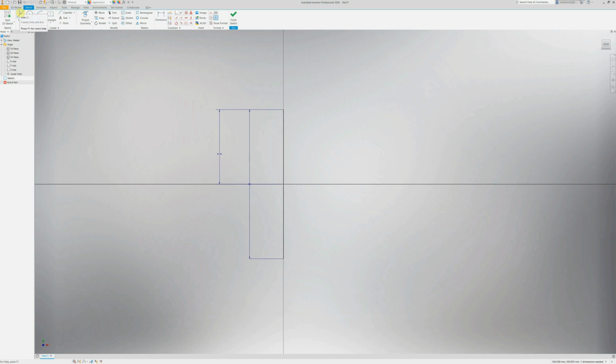So this is going to be a revolved component, so I'm going to be drawing half the profile and revolving it around this center axis. Now, to do that, I'm going to go back to the straight line, and I'm going to start from the top, the wide section at the top, and the outside diameter of this is 16mm. So I need to convert all my sizes here to radii. So 16mm diameter would make an 8mm radius. The height of it is 20mm. And then it steps down into a 6mm diameter component, so it'll be a radius of 3.